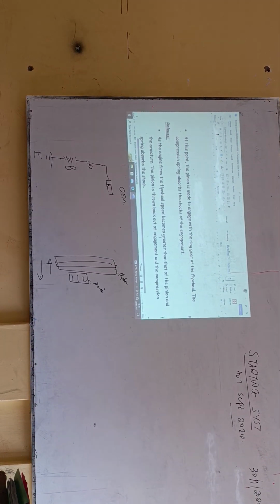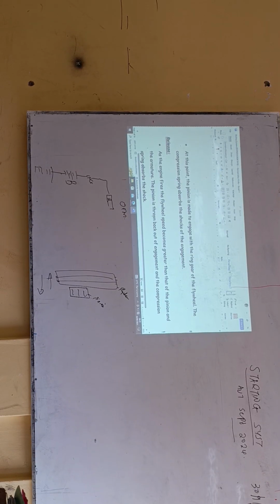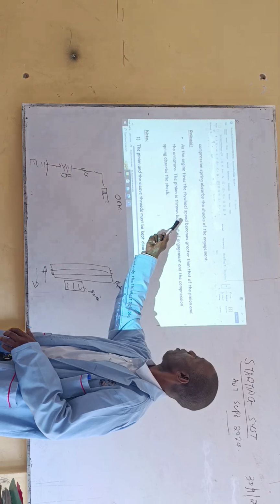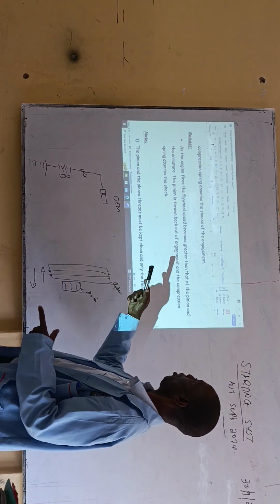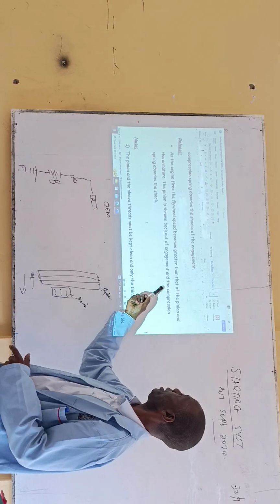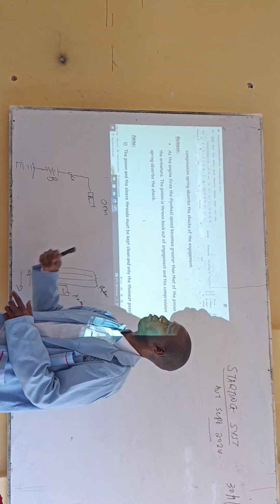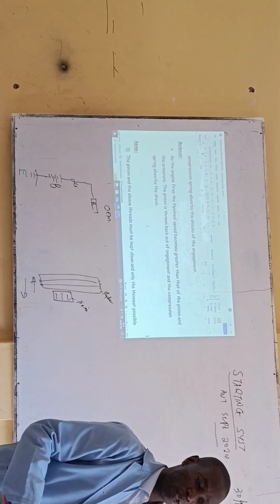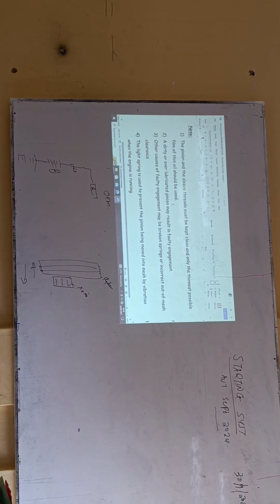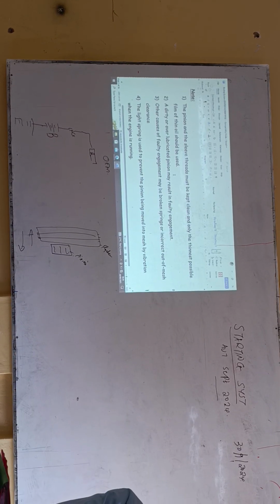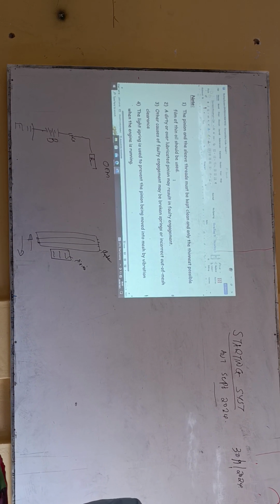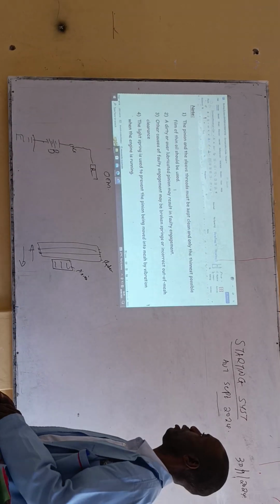So here it's all about release and engagement. On release, when the engine fires, the flywheel speed becomes greater than that of the pinion and the armature. So the pinion is thrown back out of engagement and the compression spring absorbs the shock. That is all about the release and the engagement. Some few things to note: the pinion and the sleeve threads must be kept clean, and only the thinnest possible film of thin oil is allowed.